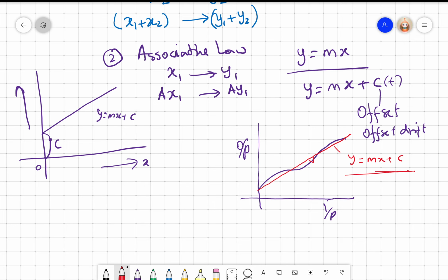What is nonlinearity? It is the deviation of the actual value of the transducer from the expected linear value. Of course, this expected linear value is something that we arbitrarily derive from the actual nonlinear characteristic of the transducer. Okay, so this is the nonlinearity error. Again, the nonlinearity error depends upon where I measure. If I measure here, I get some nonlinearity error. If I measure here, nonlinearity error equal to 0, right? And we can look at that.